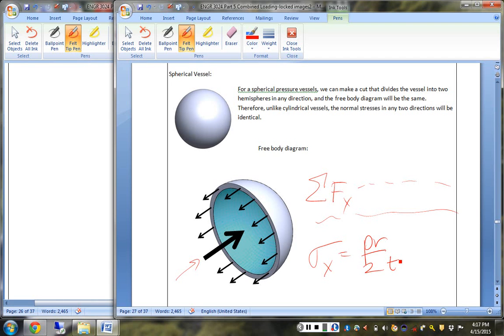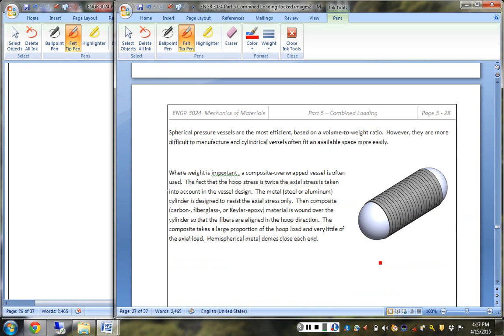Spherical pressure vessels are better at being pressure vessels than cylinders. They're just a little harder to build and deal with, because you wouldn't want your barbecue gas rolling down the hill. They are much harder to manufacture as a nice sphere. From a practical standpoint, it's easy for metallurgists to make a hot dog, and hard to make a bubble. So what do we do with that? You can wrap it to make the walls thicker in this direction with simply more material. You can augment with carbon fiber. You can do a lot of things to make it better.